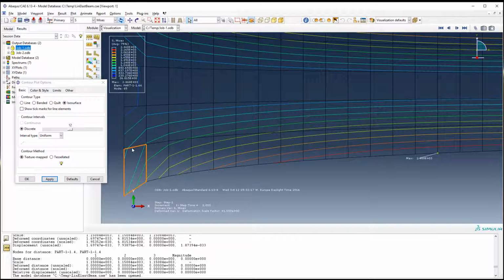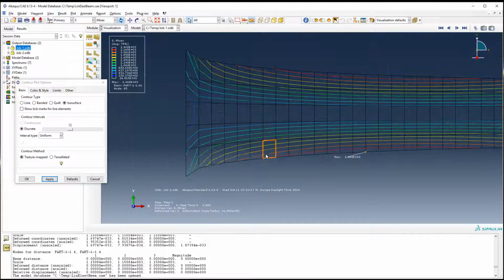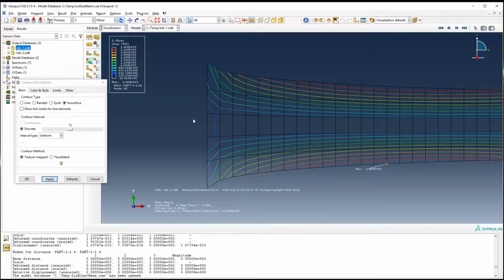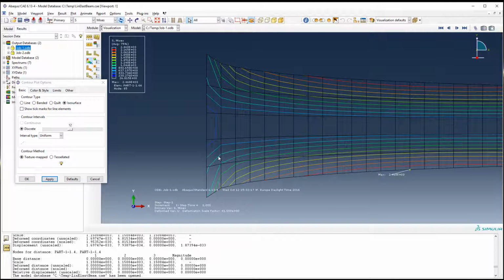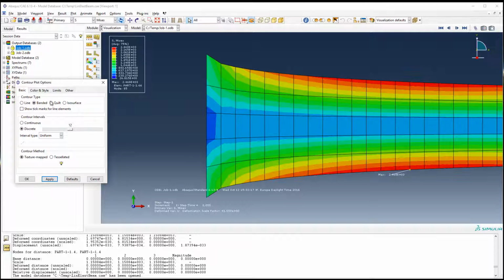If you look at the normal, it isn't smooth, and it becomes smoother if you have a higher element order. And if you, of course, increase the number of elements, then these fields will be even smoother. So if you go to banded and you go to continuous, this is a misleading picture of what's going on. It just smooths the values linearly across the elements.